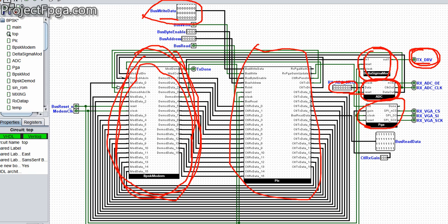That is, if you want to amplify the data at the end of the whole processing, you have to pass through here. This is also the SPI setup. I treated SPI in one of my earlier videos, synchronous serial interface. So you can just get a glance of it because I'll be touching it when I'll be talking about this FPGA submodule. This is the SPI that does the transmission. You have the chip select, the output, and the clock.